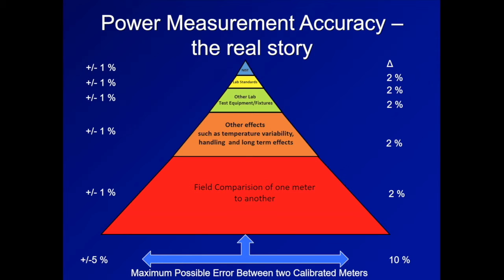Well, how do we do that? We use a piece of test equipment called a vector network analyzer, where that directional coupler is swept, and we look at coupler loss, but we also look at directivity. I'm going to talk about directivity a little later, after I get done with this slide or the next, which is a discussion of directional couplers. All right, we're using another piece of test equipment now. The vector network analyzer, you guessed it, has to be calibrated to a NIST standard.